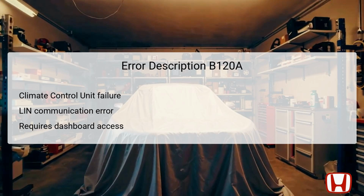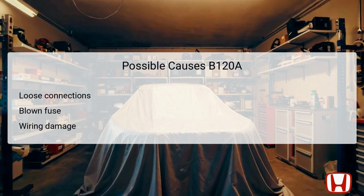Physically, the climate control unit is located on the vehicle's dashboard area and interfaces with the vehicle's network of sensors and computers. The LIN bus acts as a communication line that allows different parts of the vehicle to share information. A failure like this may not only impede climate control functionality, but also indicate issues elsewhere in the vehicle's electronic systems. There are several possible causes for the DTC B120A.